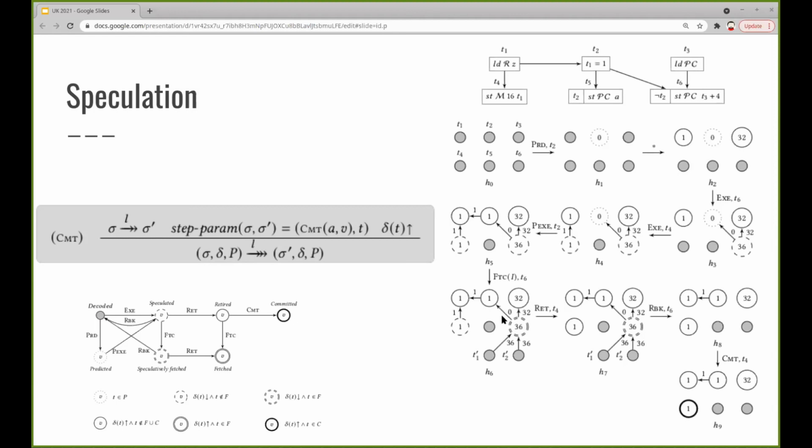So this gives quite liberal semantics because we can predict arbitrary values. We leave the processor free to roll back a misprediction immediately, or keep going and perform a nested misprediction and only later on correct this misprediction. It also allows basically to recover only part of a misprediction, in the case that a prediction of the processor speculates something correctly and something else wrongly. The processor here is allowed to only roll back part of the state instead of the whole state.